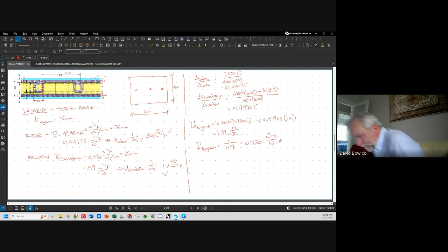Okay, remember when I said that the impact of the cold bridge on the concrete is peanuts? And it was, because the concrete is also a poor insulator. Exactly the same cold bridge, that is 3 wires passing through the insulation, reduces the R value of the insulation from 1.11 to 0.72, even though it is such a tiny, tiny area.